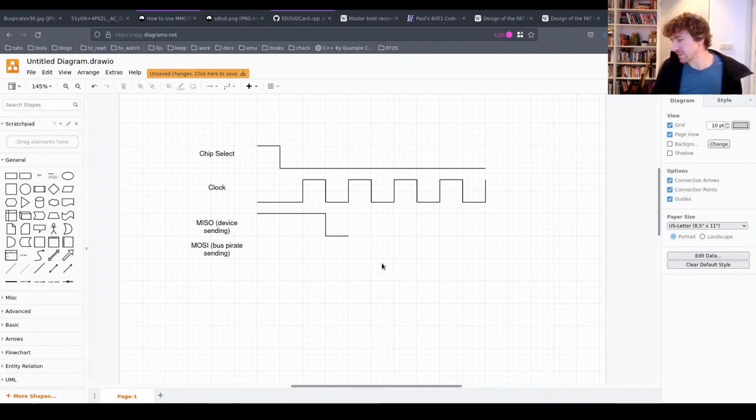I know that this discussion now is a little bit low level, literally, because we're talking about electrical lines, but it's going to become important, because unlike the last video where we were just doing SPI transfers, just sending data and receiving it, we actually need to control the signals a lot more directly, because the SD card protocol wants us to keep some lines open while we send data and then change them and send a bunch of stuff. So we need to take account of that.